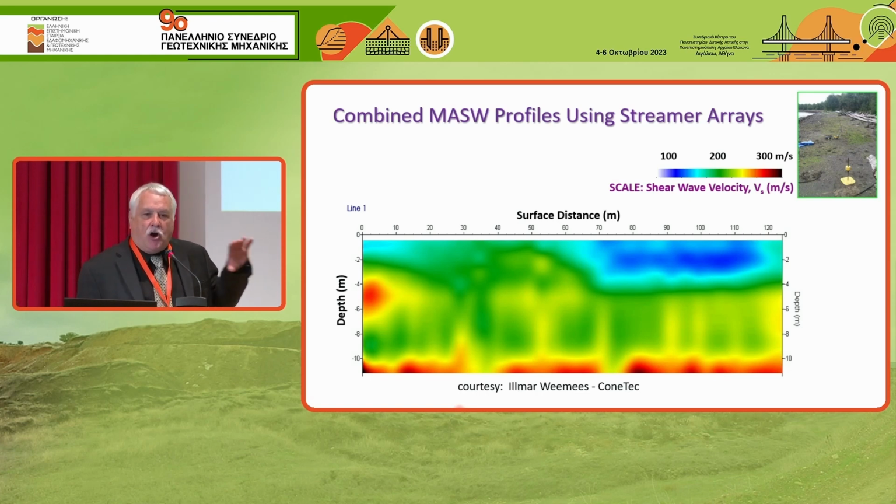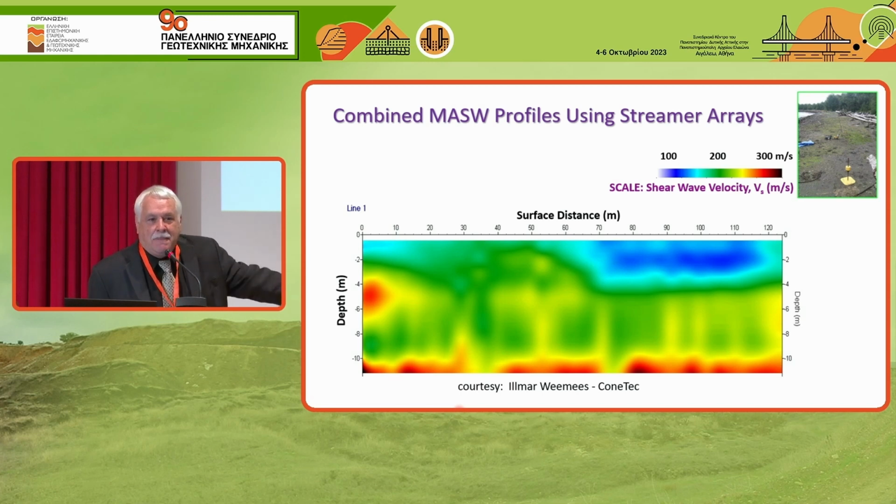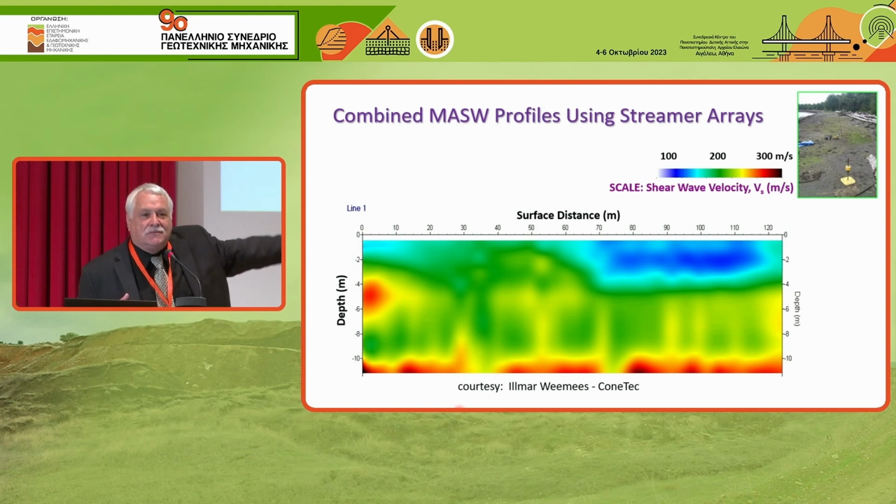So you can just see automatically where you've got a problem with settlements and or stability. You can even imagine if somebody was building a warehouse, the contour of the profile would be dipping down to the right. And because you have Gmax, you can actually calculate Gmax. You can actually start doing some calculations of that magnitude of that displacement.